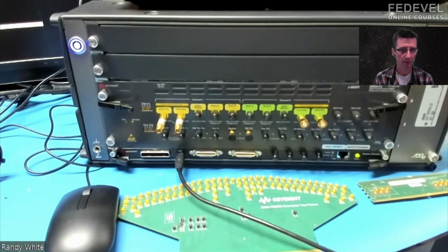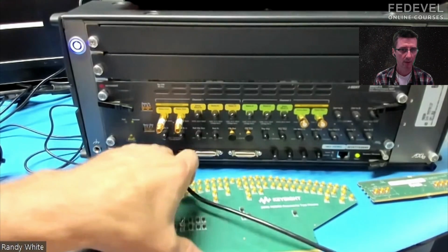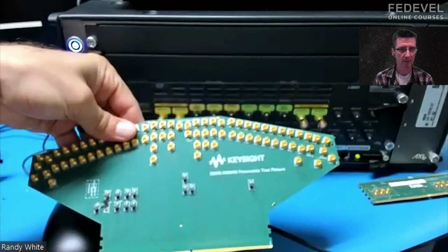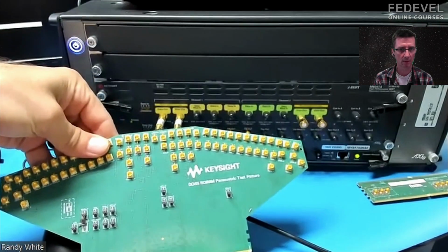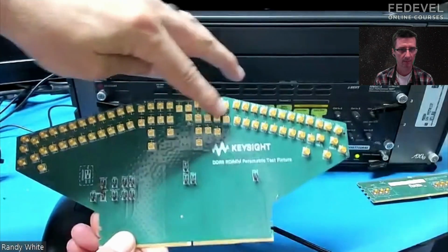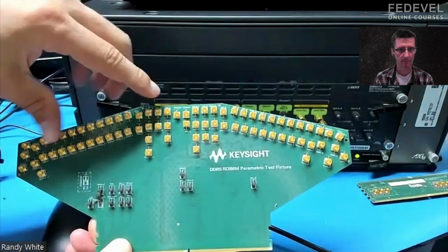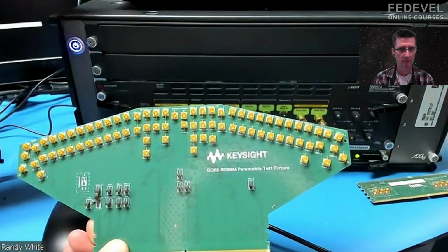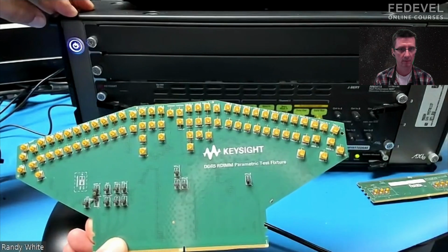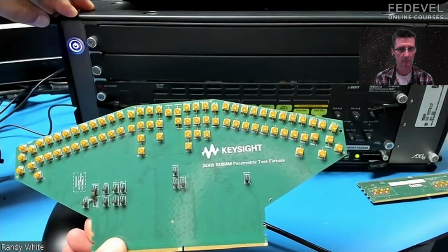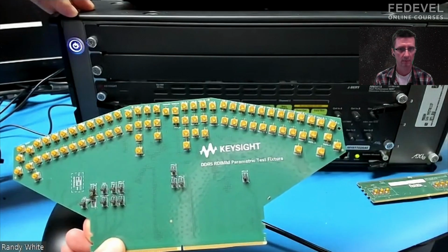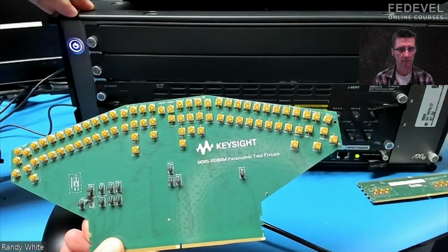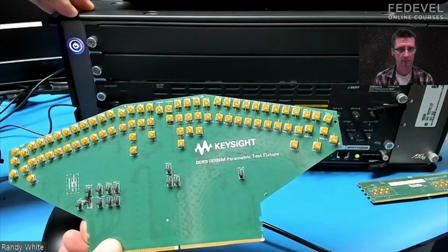Okay, and the big board on the table, this one is basically used to probe all the pins on the memory chip? Yeah, exactly. Look at all the rows and rows of coaxial connectors here. So as you know, memory, 64-bit bus, multiple DQS strobe lines. We have the clock. We have different sideband channels and auxiliary lines like alert, reset.